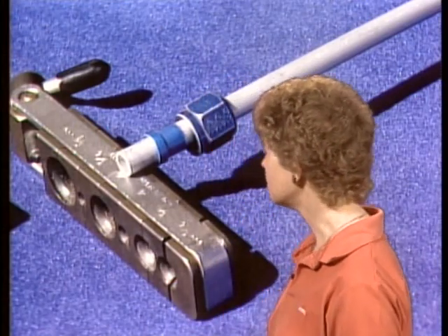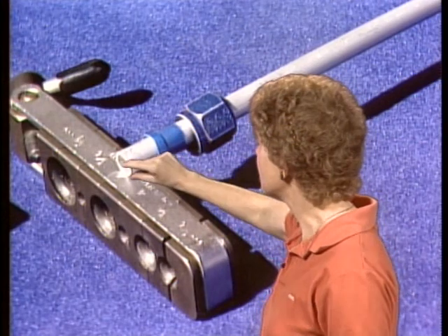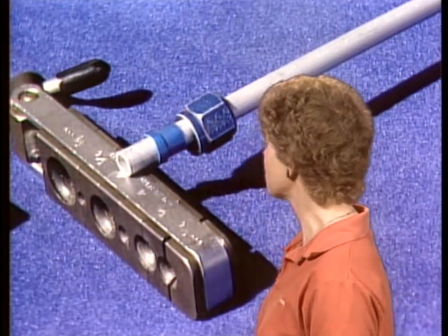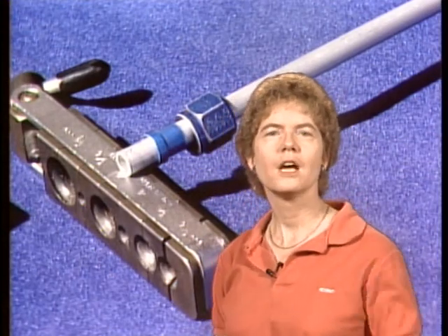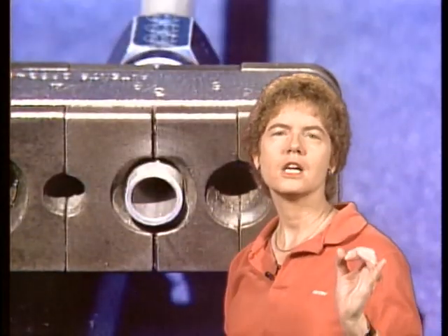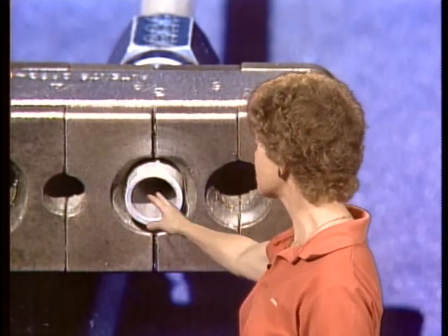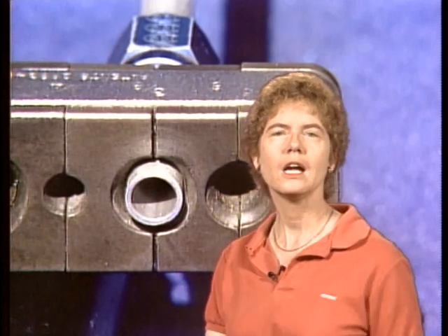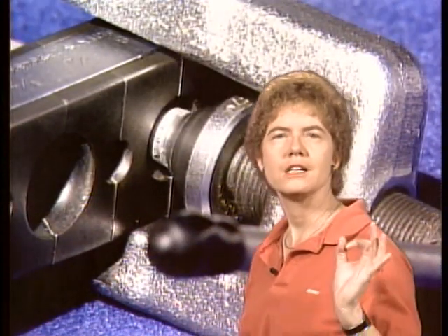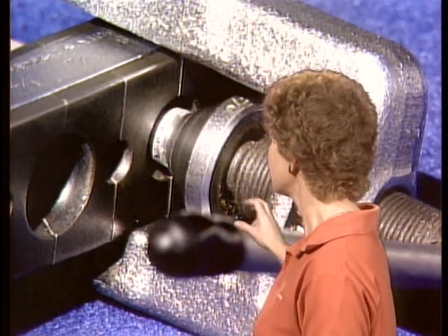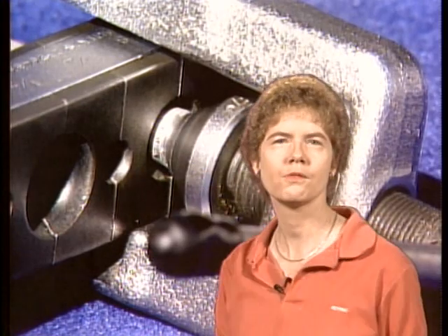First thing you're going to do is slip the fitting nut and the sleeve onto the aluminum tube that you're going to flare. Here's the sleeve and the fitting nut. You've put that on the tube. The second thing you're going to do is place the tube in the proper size hole, whichever is the proper size for that size tubing, in the flaring box. The third thing that you're going to do is center the plunger or flaring pin over the tube. So you've centered the plunger or flaring pin over the tube.